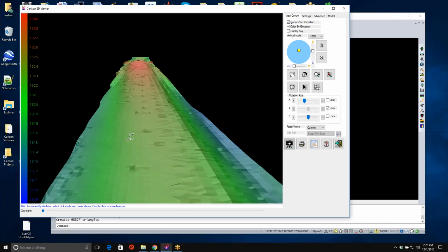Again, you can see that we have some data that we can use out in the ditches and the side slopes, but in another lesson, we'll be actually going through and getting some RTK GPS data for my shoulders, edge of pavements, and center lines, and then merging two sets of surface models together to form a composite data where I've got LIDAR data for the ditches, but more precise elevation RTK data for the roadway model itself.